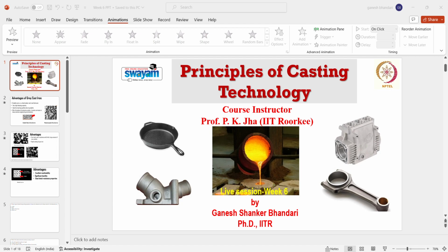But the major challenge is that you have to go with very low sulfur content iron. You have to minimize the sulfur content in that iron to less than 0.05 percent, because if sulfur is there, it is going to create iron sulfide in the structure, and you will not get the desired properties in your ductile cast iron, because iron sulfide provides brittleness to the structure.